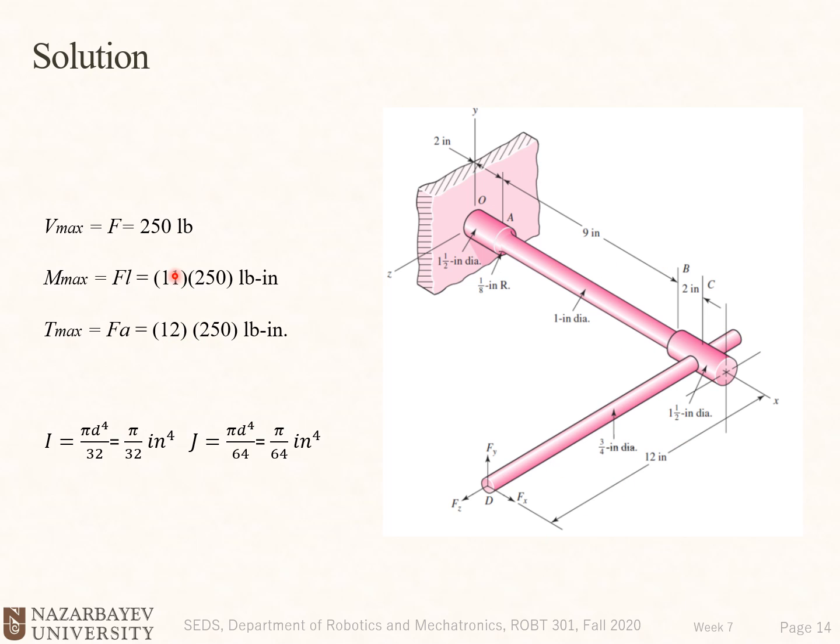For example, why do we have 11 here, not 9 or 2 or any other number, yes. And I and J are calculated based on the diameter here at this cross section, yes. So we said that although notches or fillets in ductile material don't create specifically a stress concentration, we need to take into account the radius, diameter, or cross section that they cause.